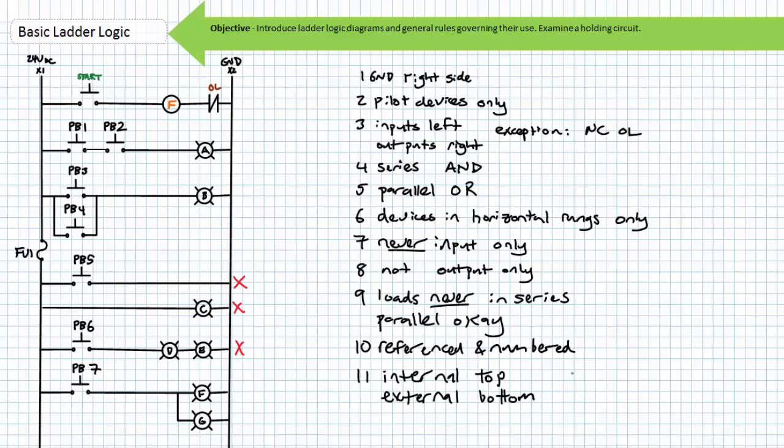Finally, and this may sound like nonsense to you right now, but you'll appreciate this advice later. All internal logical loads ordinarily appear in the top half of a ladder logic diagram, and all external output loads appear in the bottom half. An example might be an electrically controlled system using a control relay, a timer, a counter, a solenoid, and a pilot lamp.